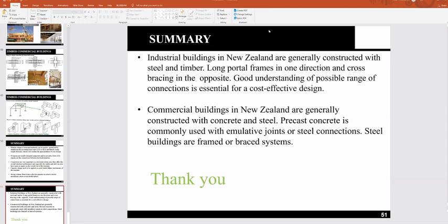Timber has to be a treated section because timber shrinks a lot, and it can have very different creep properties. So generally, the timber would be treated so that no rotting or pest attacks happen, and it is dry, clean timber. The timber can be 1 year old. As long as it's treated, it's fine. Again, we are talking about structural timber.